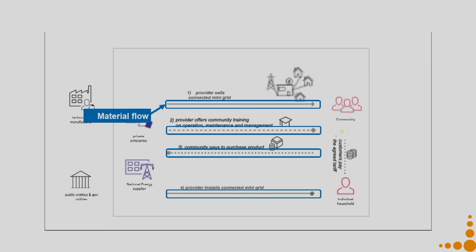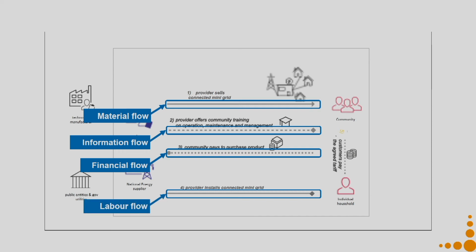We have different types of arrows. So, the material flow arrow is how the first arrow looks. It is a solid line with a triangular arrow. The second type of line and arrow is used for information flow. The third one is a dotted arrow as well as a dotted line, that is used for finance flow. The fourth one, the line is the same as the material flow, but the arrow is diamond shaped. So, that is used for labor flow.